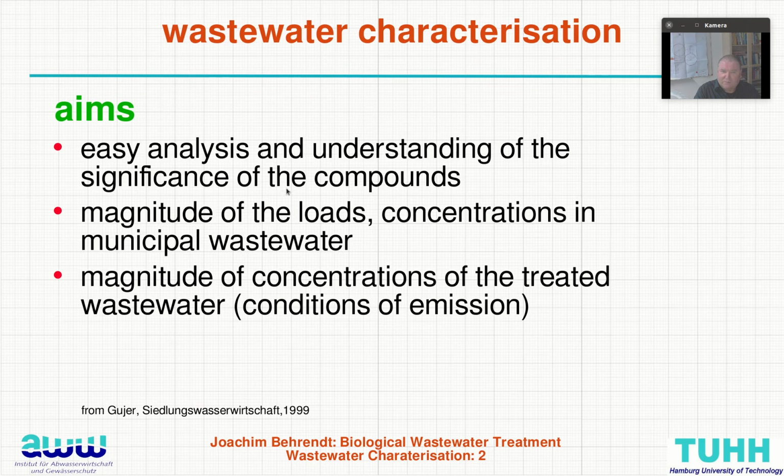Finally, what are the aims of wastewater characterization? Why do we need to do this? First, we need an easy analysis and understanding of the significance of the components. Then we have to calculate the magnitude of loads and concentrations in the wastewater. And of course, we also need knowledge about the magnitude of concentrations in the treated wastewaters. Finally, we also have to control the emissions.